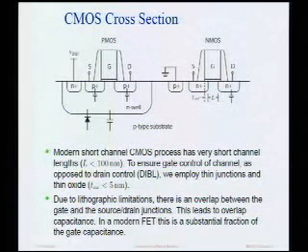I misspoke earlier. In a PMOS device, I can just connect source to my body, and as we'll see, that effectively turns off the body effect. But in an NMOS device, I don't have that option. Because this is a reverse bias junction, I have to ground all my body nodes. And that means that if I have source nodes which are not grounded, I will get the body effect. And we'll see that later on.